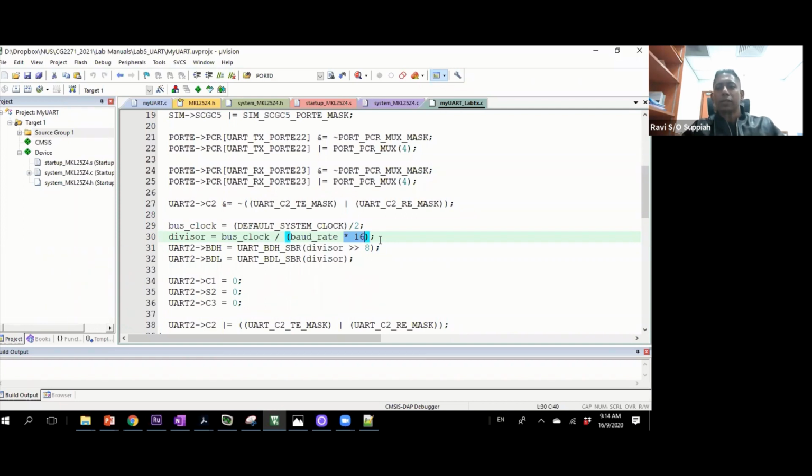Correct. Okay, so good. Some of you remember the oversampling. The UART module internally does oversampling of the data. The reason is to help minimize error due to any noise or interference in the signal. So oversampling, and then you take the max mode kind of a response, gives you a higher chance of getting it correct. So this divide by 16 is something you may not see in other calculations or in other controllers. This is unique to this controller because of the oversampling.